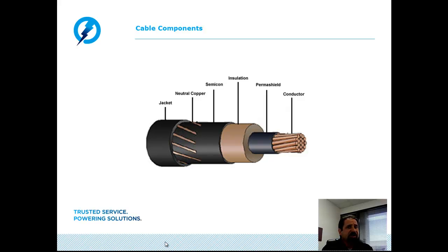Insulated power cables are used for transmission and distribution of electricity for various underground applications, residential as well as commercial. In a typical medium voltage cable, copper or aluminum wires, either stranded or solid, are used as the conductors. These conductors are covered with an extruded polymeric stress control layer made of semiconductive compounds, often referred to as the strand shield or conductor shield.